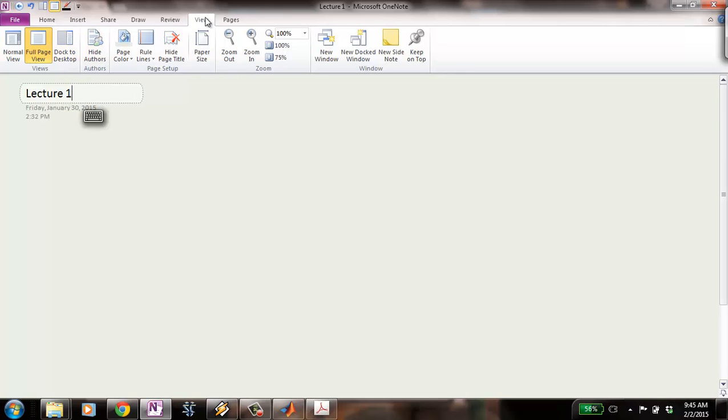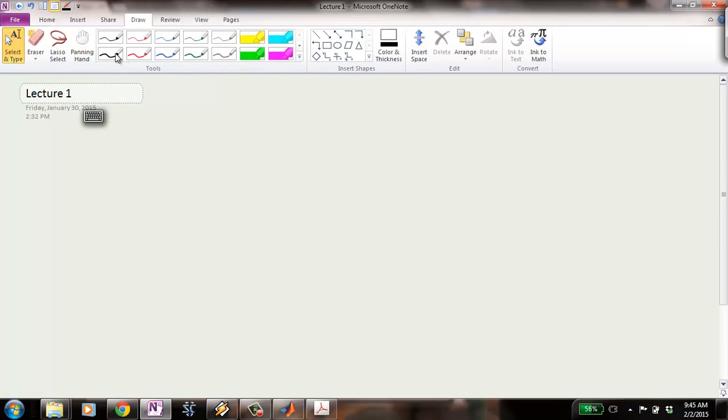Let's just, boy, what can I do in a few minutes here? Well, so in general, we're not going to restrict signal values to be real value. They can be complex values. There's a very important reason why we're doing that. Okay, you might say, well, real world signals are real numbers. Yeah, you don't have a sensor that gives you a complex voltage. It's got a real number voltage, right? But if you extend things out to complex numbers, the math is a lot simpler when you're doing things like Fourier transform. The Fourier transform is going to explicitly use complex numbers everywhere.